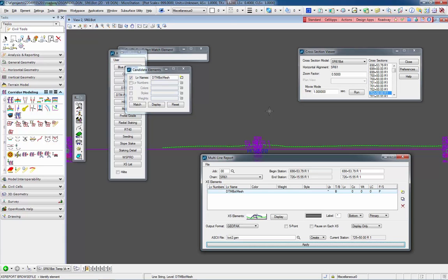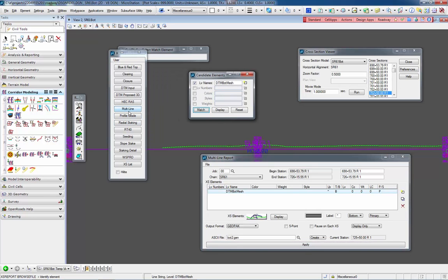So it's just a combination of changing the design stage to a top mesh, bottom mesh, cutting the cross sections, and using either the report tool in SS4 from the end area volumes .xml, or using the legacy multi-line report tool. So hopefully this helps.